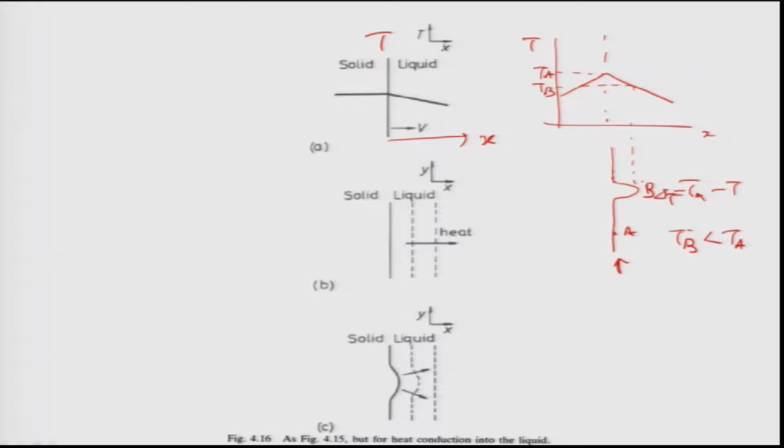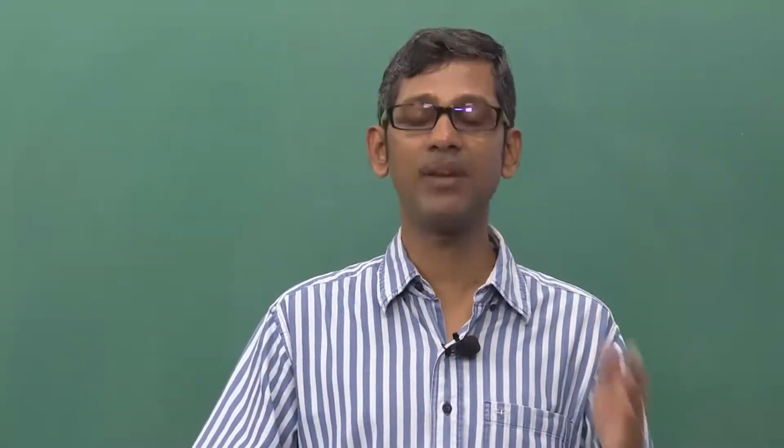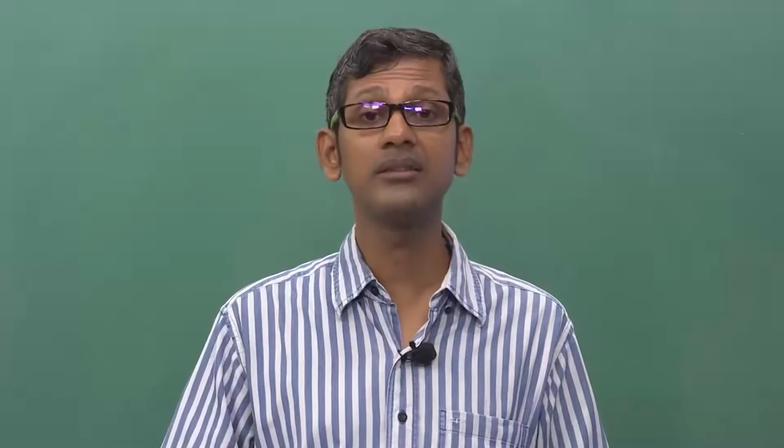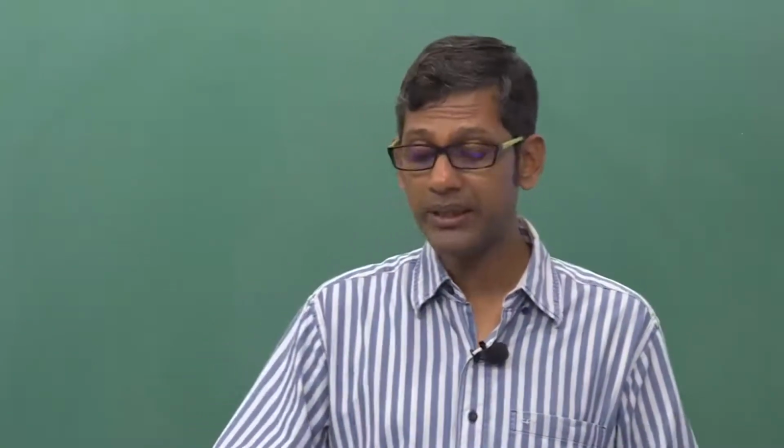As B is getting undercooled more than A, B will have more driving force to grow. So, therefore, the protrusion which is formed on the interface as shown here will grow, and this protrusion will lead to the breakup of the interface, which was flat in the earlier case when the temperature gradient in the liquid was positive. It will now break up and form this kind of large protrusions on the surface. Remember, these protrusions can easily form like this.